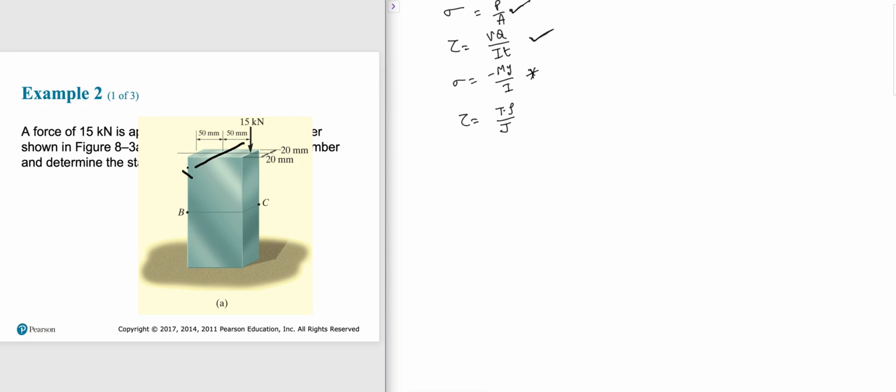Let's say this is x-axis. So with respect to x-axis, isn't it causing a moment? It is. That means 15 kilonewton is not just a compressive force, but there is also a moment acting like that, which is being caused due to the 15 kilonewton force.